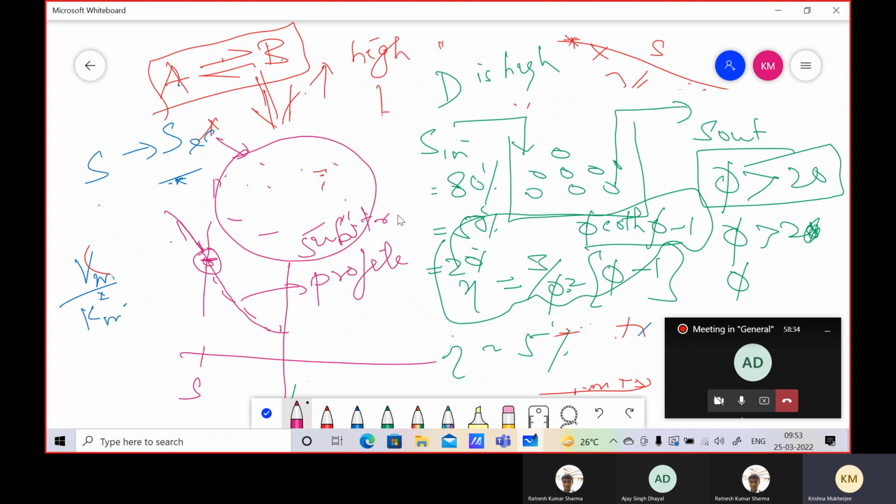This is the substrate profile inside the bead. Given the substrate profile inside the bead, we took the derivative of the substrate profile at r equal to R, and that was the matching rate of substrate coming inside, and that is how we found out the net rate of reaction. That's what we did, right?